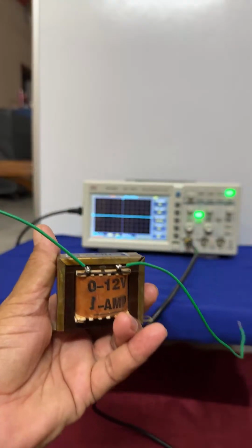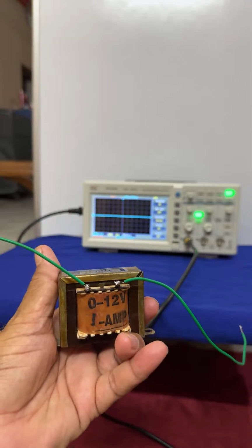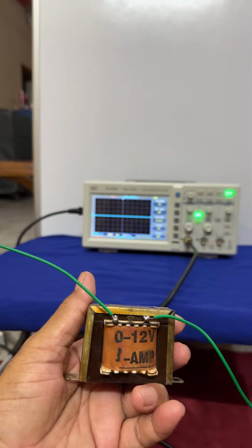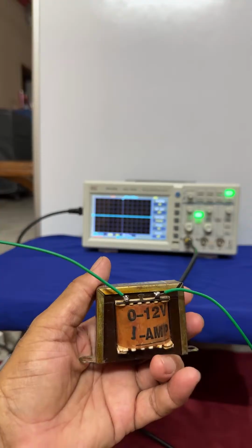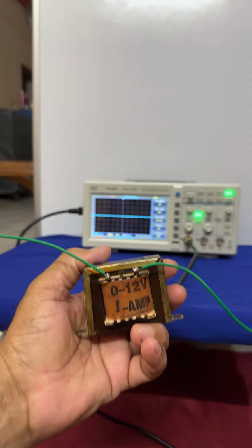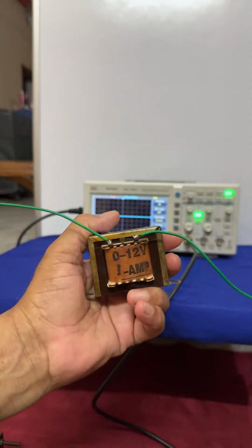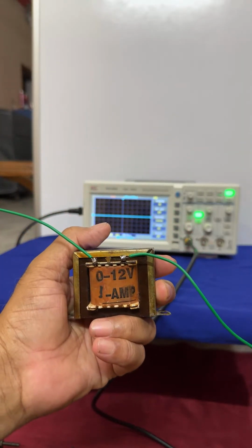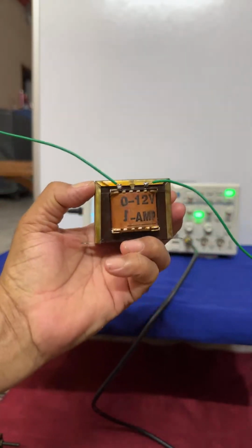And I have connected two wires to these two terminals. Whenever AC comes, pulsating DC, containing some components of AC, will be allowed through these. We will observe again through the oscilloscope. The graph will change a lot. So this component, remember, is called an inductor. In the filter circuit, this is called a choke coil.